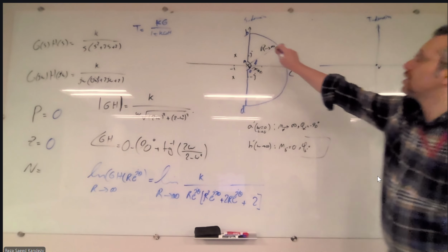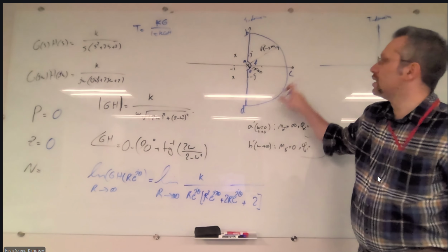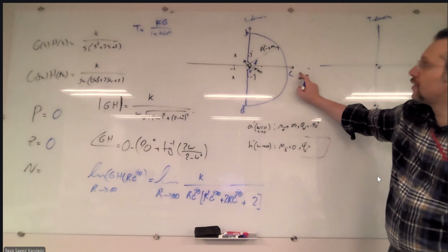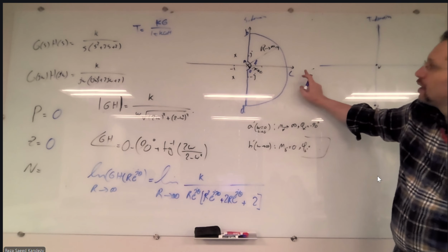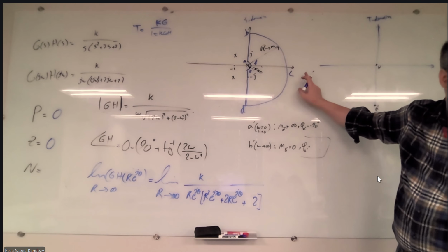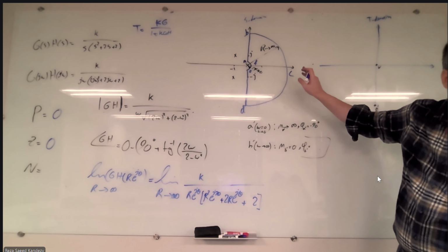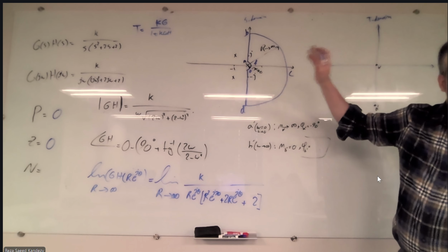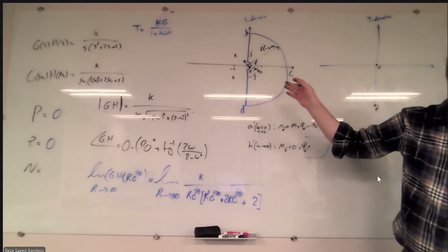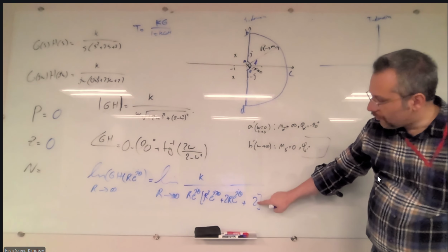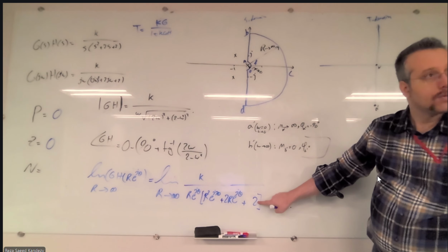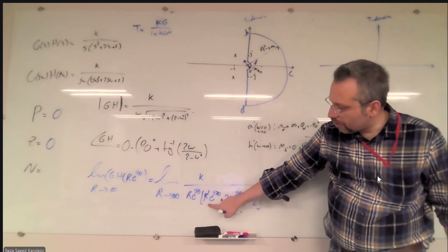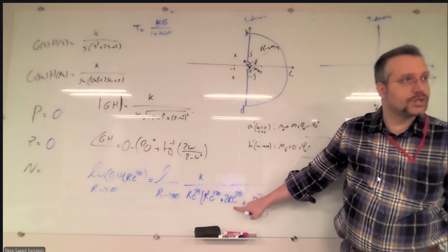We want to consider the points B, C, D at infinity. So instead of considering a value of infinity for that, we simply limit S to R e^{jθ} when R is infinity. Instead of the exact value for the function, we limit that. Now, if R goes to infinity, this one is absolute. This one compared to this R squared is also negligible.